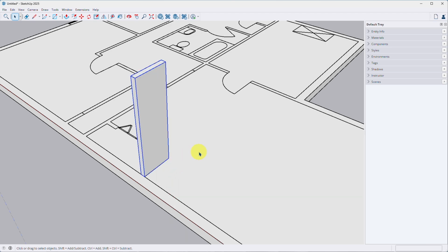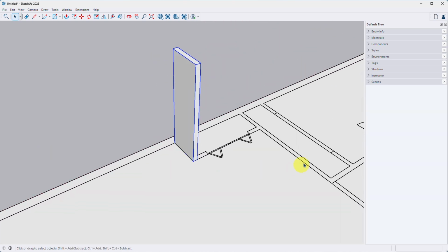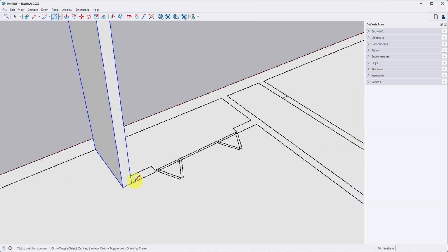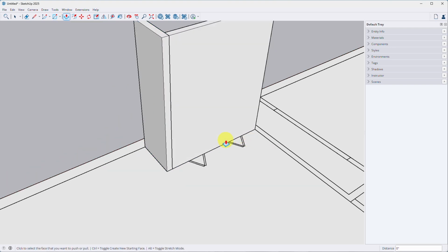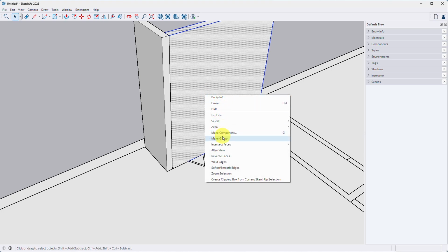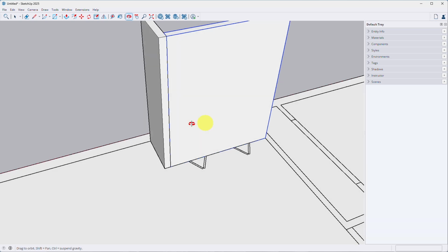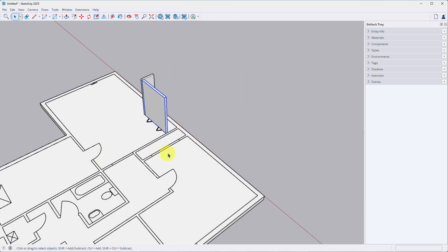Now let's make the second wall. Repeat the process by creating a rectangle for the base, using the points of the plan as inference points. This time, once we've selected the push-pull tool, all we need to do is double-click on the surface, because SketchUp remembers how far we pulled last time we used the tool. Then, clear the tool by tapping spacebar. Then, triple-click the object and make it a group. Now we can repeat the process for every internal wall on the basement floor.